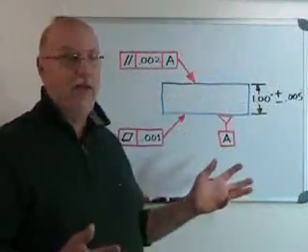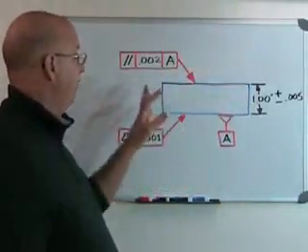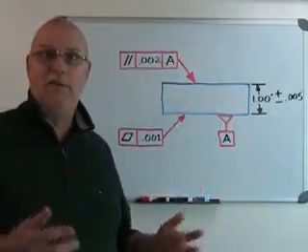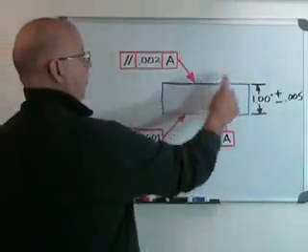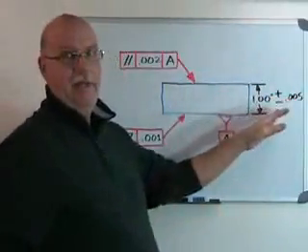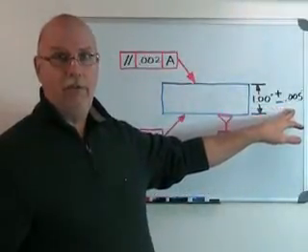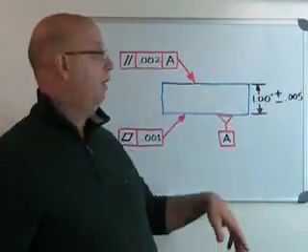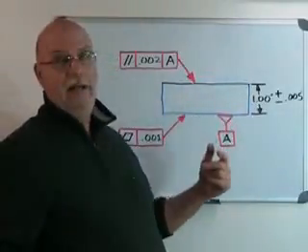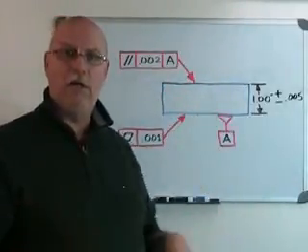So here we have a little sketch of our parallel bar in blue here, and everything's out of whack. I mean, my tolerance and my dimensions are way too big for the sketch, but I want things to be visible. So here in blue is my parallel bar, 1 inch plus or minus 5 in black. That's my dimension and my dimensional tolerance, 5/1000ths of an inch plus or minus to 1 inch. So 1 inch 5/1000ths, right down to 995/1000ths of an inch. Anything in there is good as far as height goes.